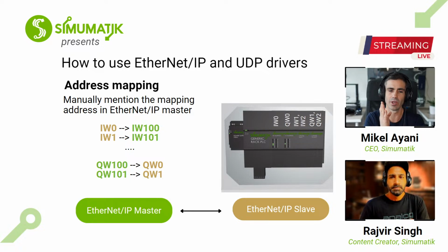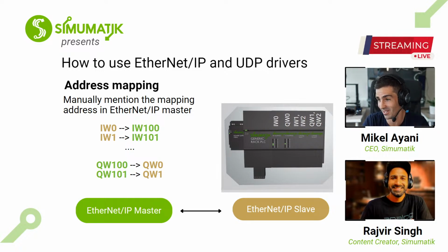So we have a local addressing which, once transferred to the PLC, could be another address. And I know this sounds like a mess, but we will see it soon with an example in Codesys. So it's different, and it requires changing a little bit the way of thinking when we use this kind of driver, but it's really, really powerful, and the latencies are really, really low. So these are very, very quick drivers.